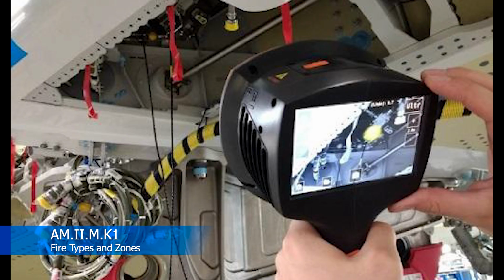With bleed air, you're sending extremely hot air into the aircraft, and if you have a leak somewhere, it's going to be blowing that hot air on any number of things. Keep in mind that the only thing really stopping everything from catching on fire is the temperature it's at. Once it hits a flash point, it's going to start to catch on fire. So let's say you have bleed air at 500 degrees Celsius, and the flash point of this combustible material is like 125 degrees Celsius. That material is basically inert in most cases, but whenever bleed air gets exposed to it, it's going to catch on fire. It's well above its flash point.